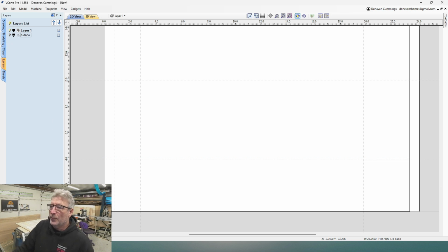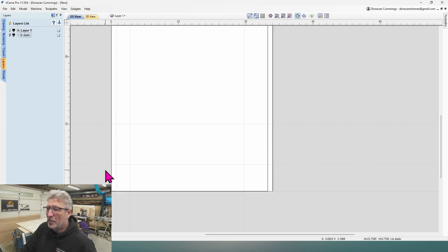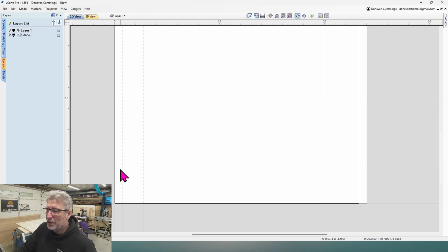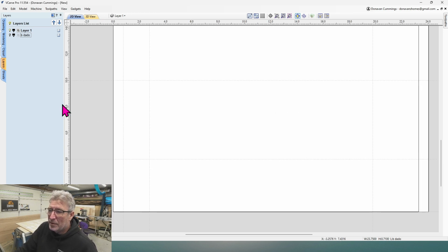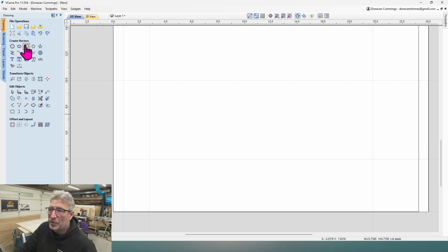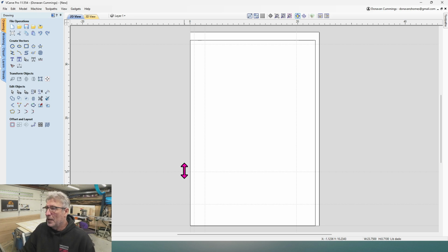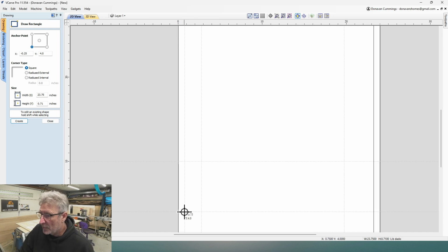I don't have to see that anymore. So my next one is going to be, I'm going to go back up to my drawing tool. I'm going to hit F for fit and get me back up to the right size. And I am going to do another box. This time I'm going to come from, and I've got my snapping on, so it's snapped to 0.75 and 4 inches. And I'm going to bring that up.